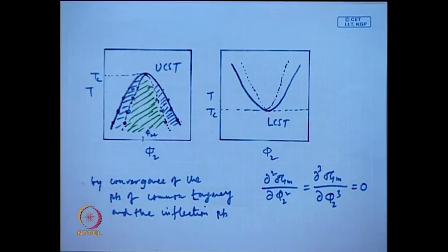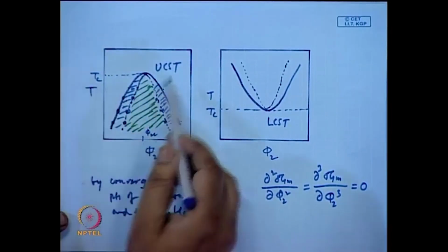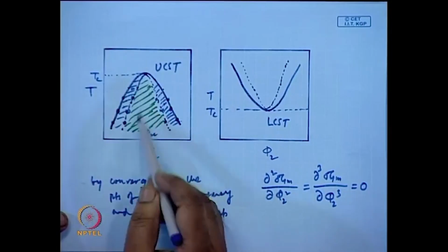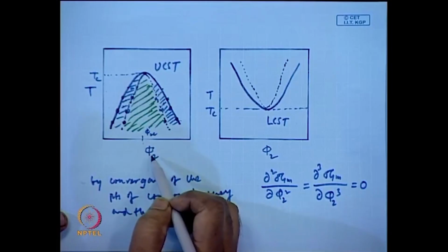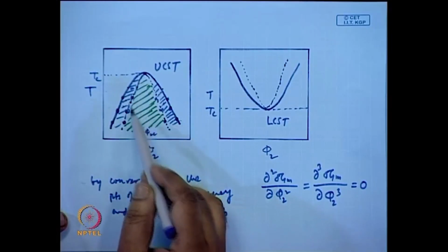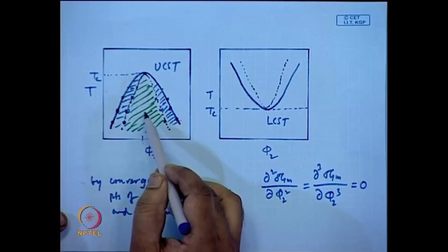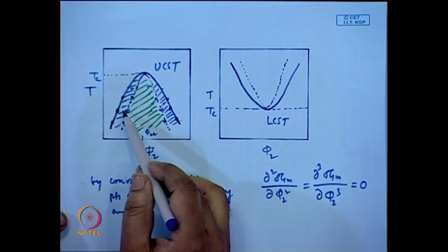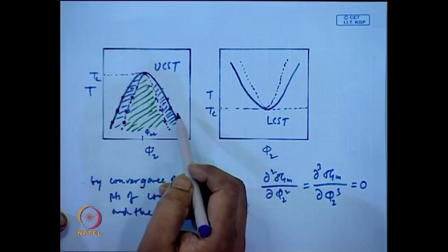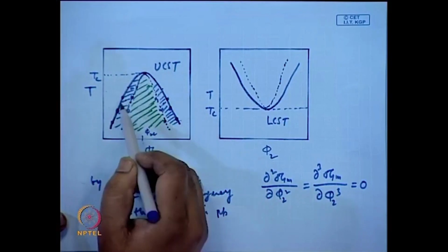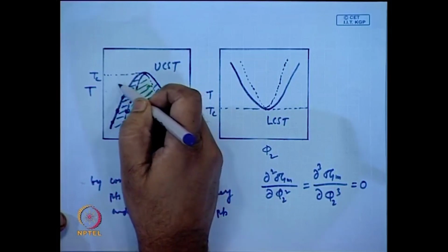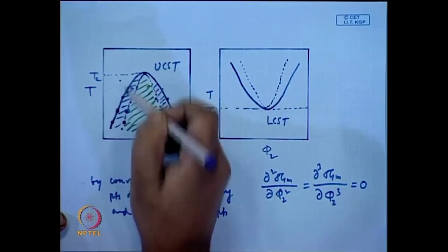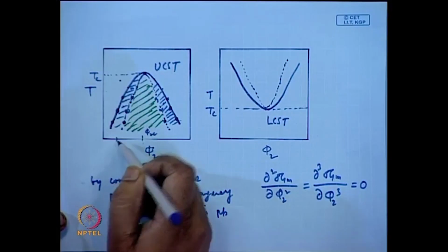So, this is basically a plot of polymer phases with temperature changing and with different composition. This is the region which is unstable, or a two phase system. This is a metastable system, which is thermodynamically unstable but metastable, and outside this is completely stable. Now, if you start from a point here, a composition corresponding to this,